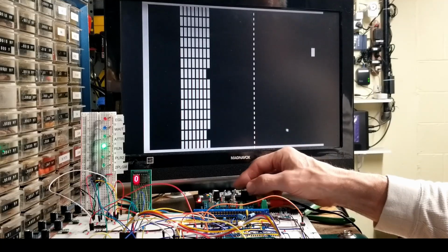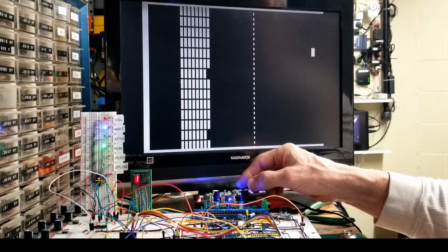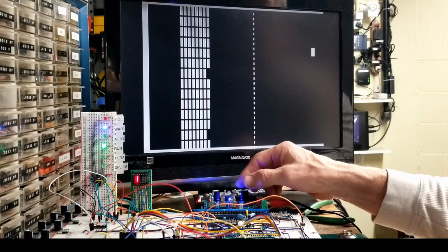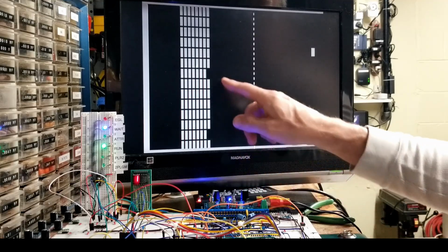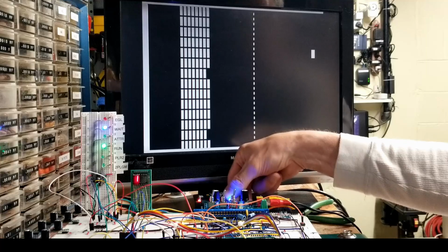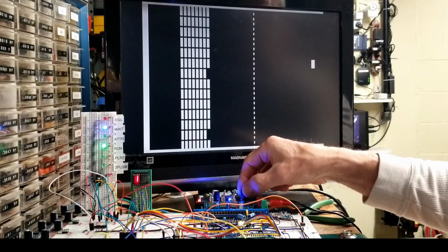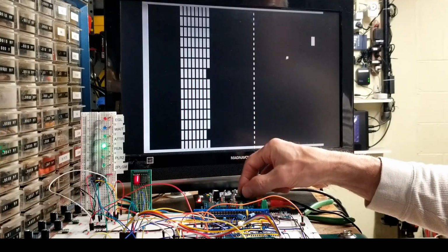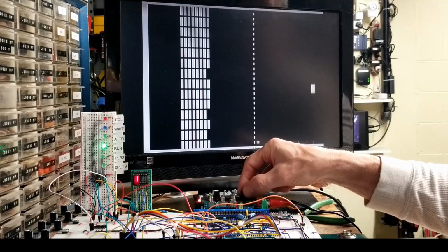Allow the ball to miss the paddle, and the circuit transitions back to serve wait, and increments the ball and play counter. We're finally at the point where we can play an entire game cycle with the proper controls and behavior. We've pretty much tested everything except flip screen.